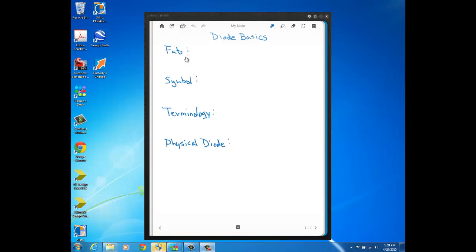Here in our first 321 lecture video, we're going to talk about diode basics along with the basic operation of a diode. So first of all, in order to fabricate a diode, you just put together two pieces of semiconductor, where one semiconductor is p-doped and the other semiconductor is n-doped. And we call this a p-n junction, where the p and the n material meet. And whenever you have a single p-n junction, you have a diode.